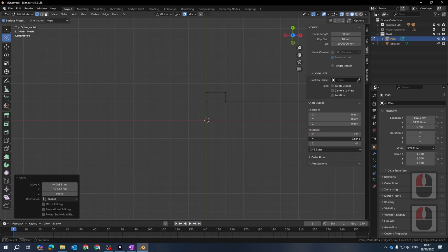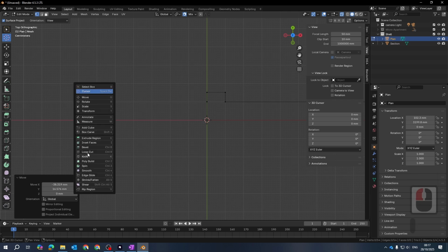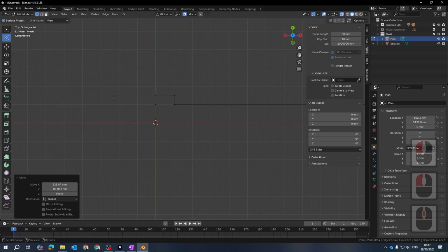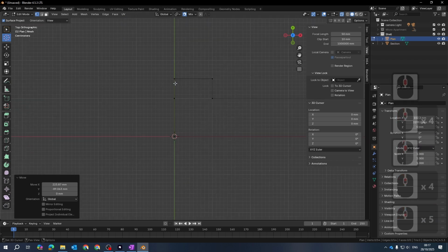That's very handy. Just understand that your cursor, if you go to view settings, can adjust. You'll see that the cursor is moving. It's hard to see at the moment, but you'll see that it is rotating. Just use your backspace command to make sure that these are always set to 0. You can also move the cursor by using this option. You can simply select the cursor tool and then move it to wherever you want to. If you press Shift Spacebar, you get a whole lot of other commands as well. Blender is quite interesting. You can set it up to work in any way, but it takes a bit of practice to get the hang of it. But just understand that you can set your cursor by using the snap tools as well. You don't have to use Shift S. That's just a shortcut on how to do this.